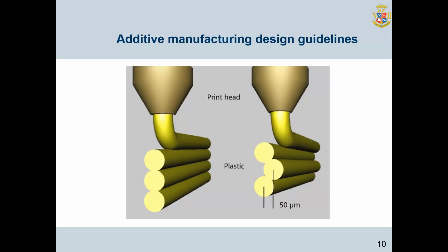When talking about the accuracy of the printer, they mean the positioning accuracy of the print head, which depends on the control scheme and the quality of the mechanical components. The higher the accuracy, the better the side surface of the model will be. The figure shows schematically what happens to the side wall if the positioning accuracy is insufficient.